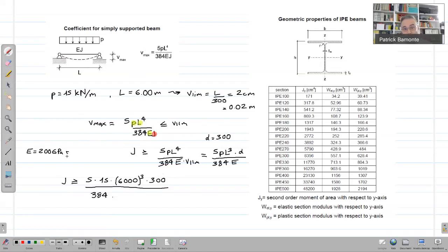Knowing that, as specified previously when I showed you what you were supposed to write as regards question 1, since we know that megapascals are Newton over square millimeter, it is convenient to convert this number in Newton over square millimeter, so megapascals. The relation between a giga and a mega is that giga is 1000 mega. So what you have here is an elastic modulus, which is 200,000 megapascals.